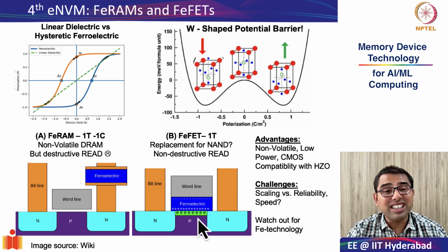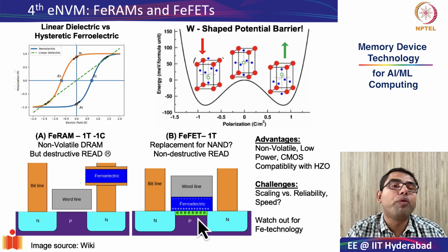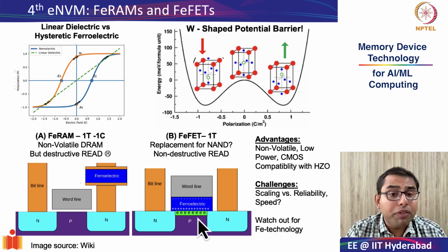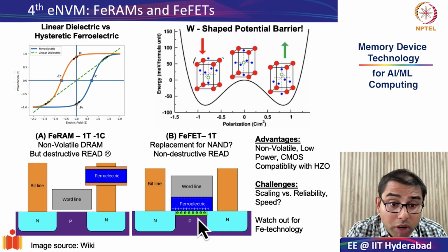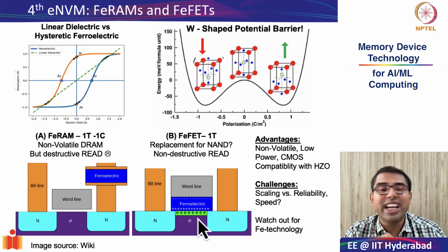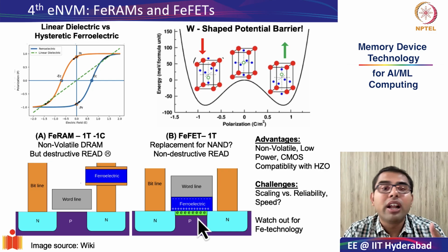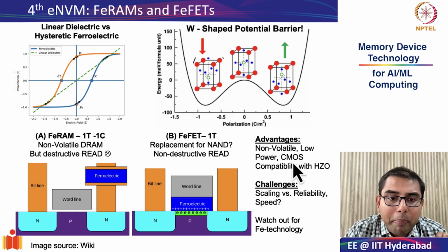However, we should understand that while there are several advantages to ferroelectric FETs, they come with their own set of challenges. First, let's discuss the advantages. As we discussed, they are essentially non-volatile, and even the switching is ultimately much lower power compared to other eNVMs. And what has really changed the game is the CMOS compatibility.